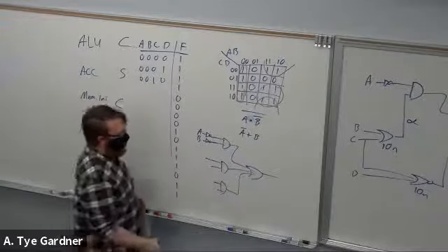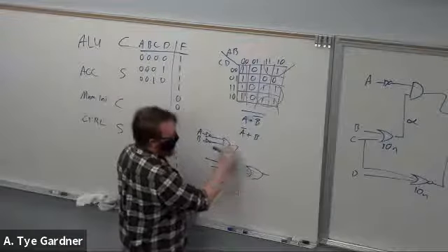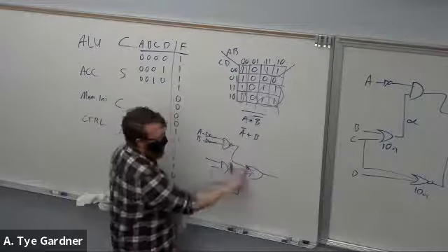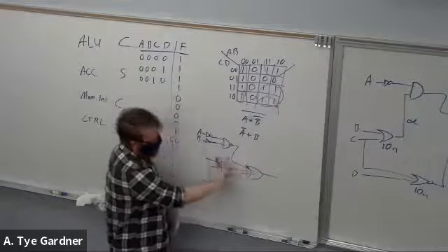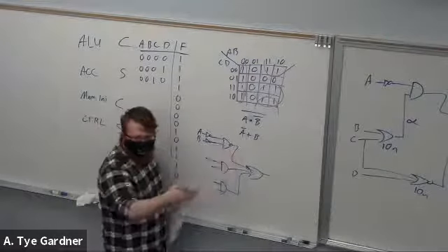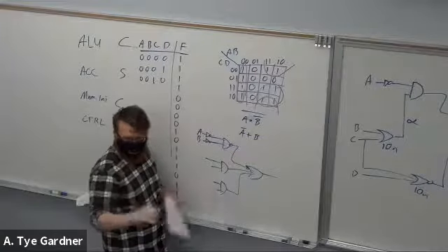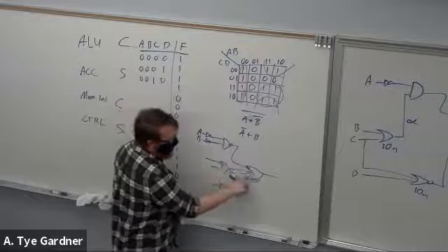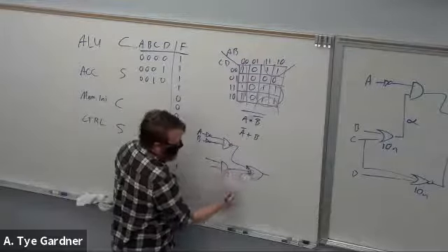Okay. And then the next question is convert it to strictly NAND gates. Okay, you read it on the circuit and we do the bubble pushing, right? That's all I'm going to ask of you. Put a bubble there, put a bubble there, right? That's equivalent to putting 2 bubbles there and pushing it back along. Not is the same as staying the same as a buffer, right? So that's all that's doing. Repeat with the other 2.